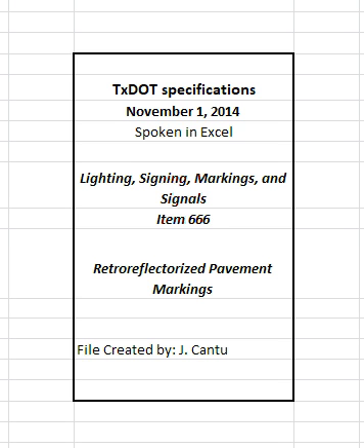4.3.2 Type II markings. Apply on surfaces with a minimum surface temperature of 50 degrees Fahrenheit. Apply at least 20 gallons per mile on concrete and asphalt surfaces and at least 22 gallons per mile on surface treatments for a solid 4 inch line. Adjust application rates proportionally for other widths. When Type II markings are used as a sealer for Type 1 markings, apply at least 15 gallons per mile using Type II drop-on beads.